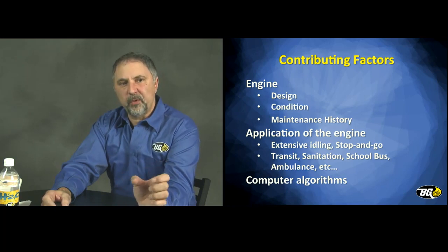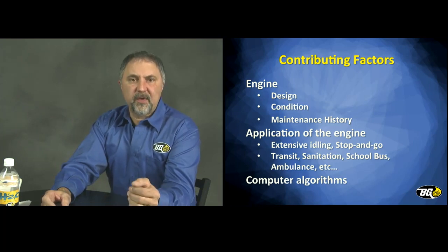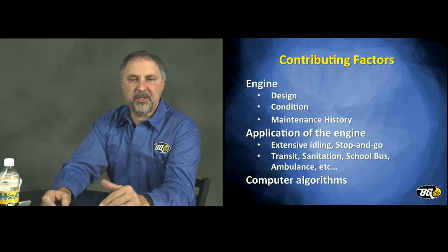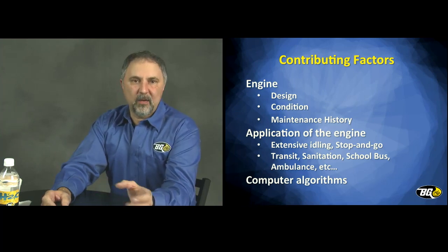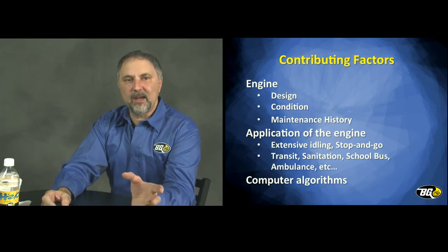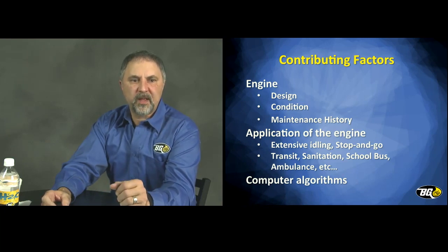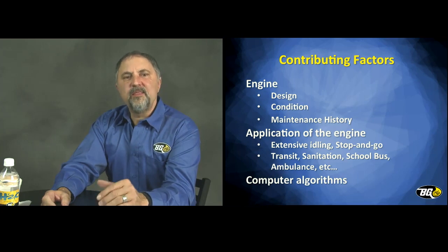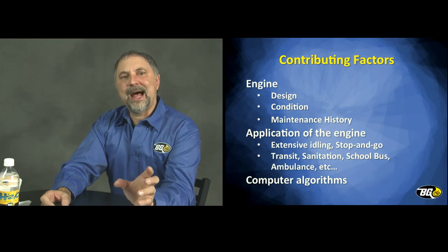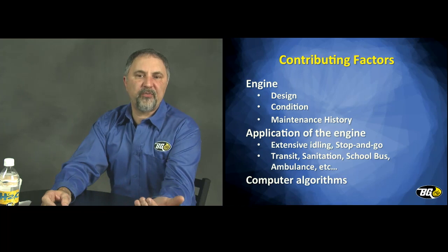And that's what I like to focus on, especially if you're dealing with an OEM. It's not the engine's fault, it's the application of the engine. And often their hands are tied, they can't change that. Because diesels aren't meant to idle extensively. So if you can think in your mind's eye, anything that would be idling, such as an ambulance or a transit bus or a school bus, anything that does extensive idling, that will contribute to the soot buildup. So they're often calling upon the OEM to change the algorithms in the computer programming, to force these things into regen more frequently.